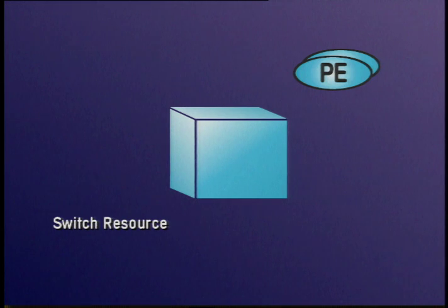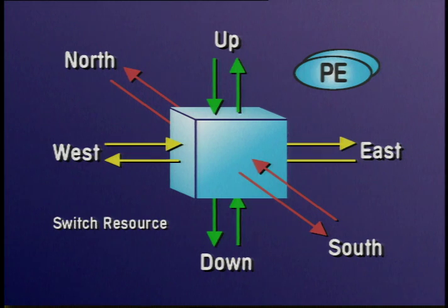There are high-speed channels radiating from the network switch in 7 directions. 6 of those directions are for the 3D torus connections. The 7th direction is the channel to the PEs. Each channel is actually 2 unidirectional channels that operate independently. In other words, it's possible to have data streaming through the switch from east to west at the same time other data is moving from west to east.